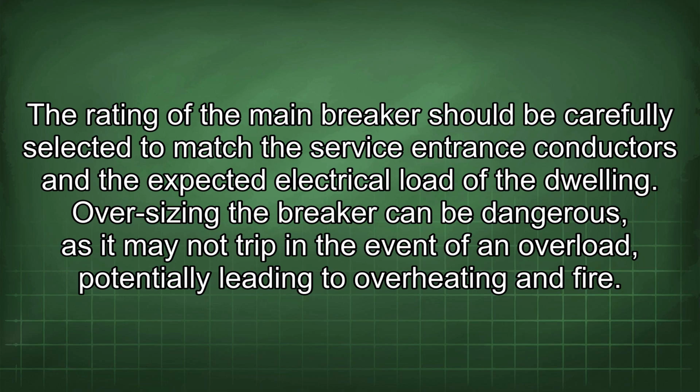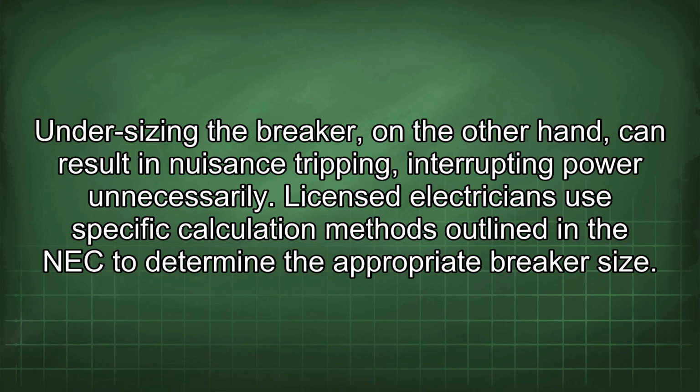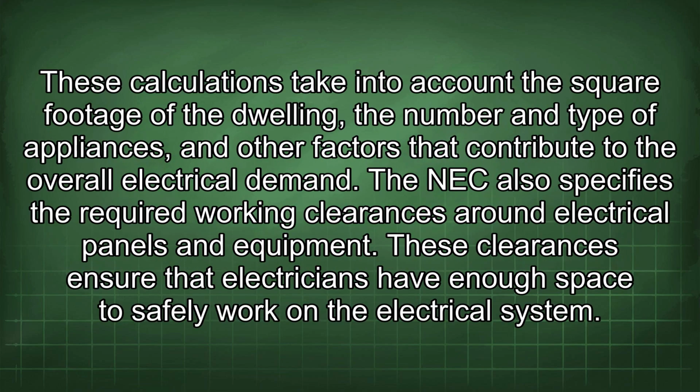Oversizing the breaker can be dangerous, as it may not trip in the event of an overload, potentially leading to overheating and fire. Undersizing the breaker, on the other hand, can result in nuisance tripping, interrupting power unnecessarily. Licensed electricians use specific calculation methods outlined in the NEC to determine the appropriate breaker size. These calculations take into account the square footage of the dwelling, the number and type of appliances, and other factors that contribute to the overall electrical demand.